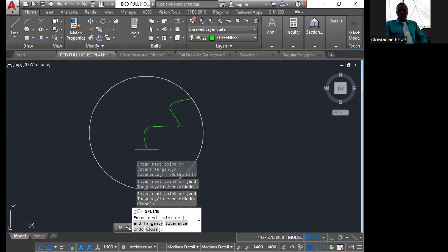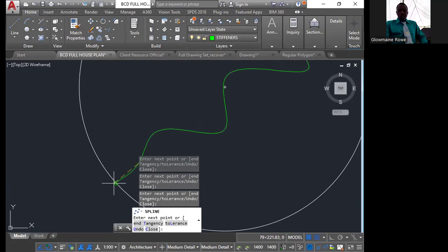And this is how you also draw your electrical wires in your electrical plan. If you're not picking up an endpoint, like myself here, you can just draw it past the circle and then trim it off afterwards. But if you find an endpoint, you simply press enter.